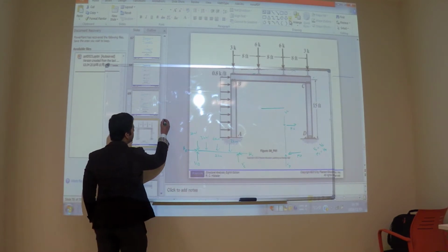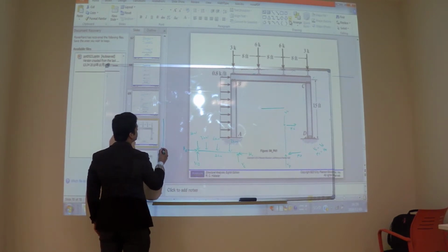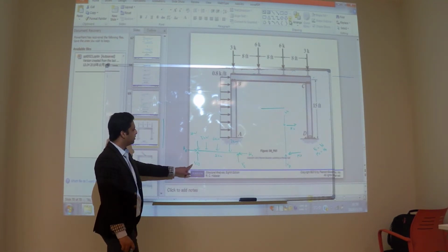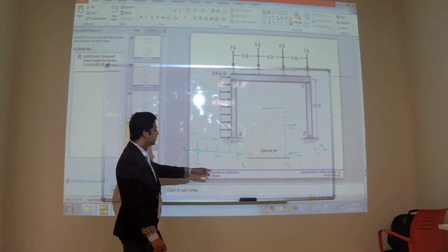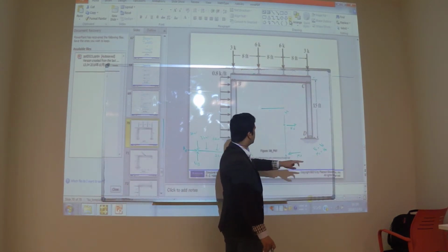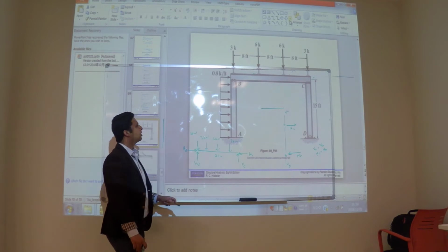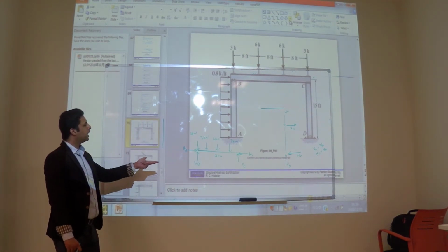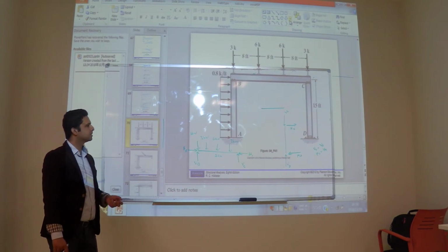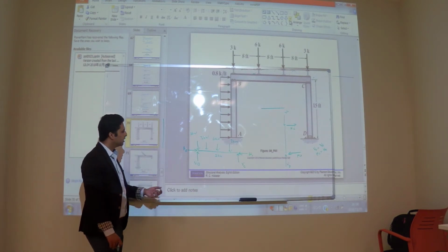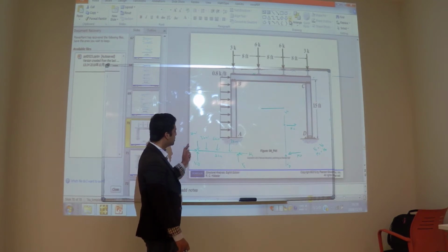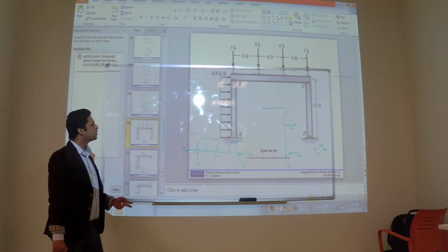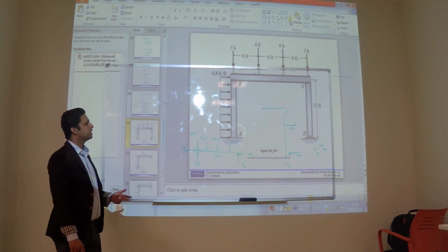And once you have VB, now come to this member. Now, for these two members, like this member and this member, you can draw the shear force and bending moment diagram. If you apply sigma Fx, HB will equal HC, which is also equal to HD.